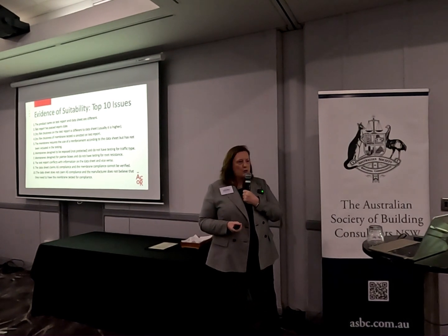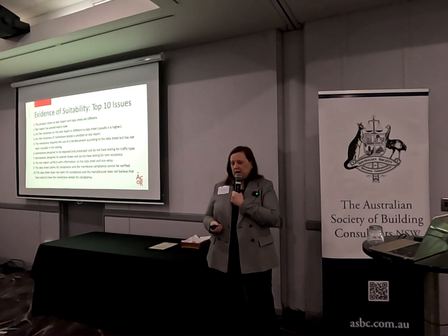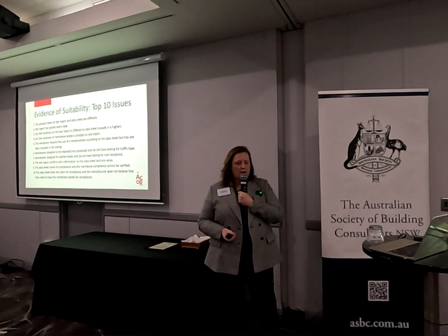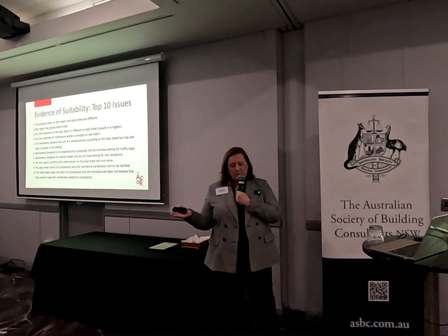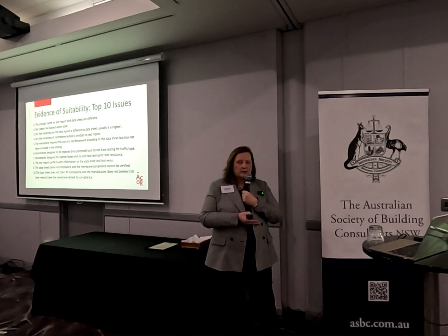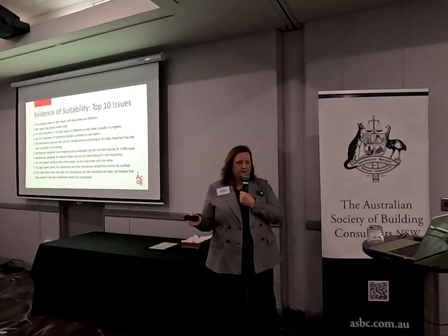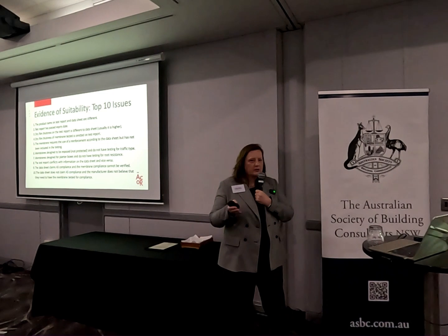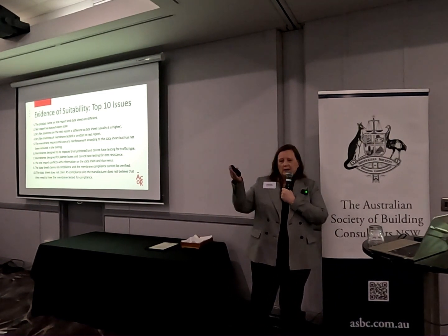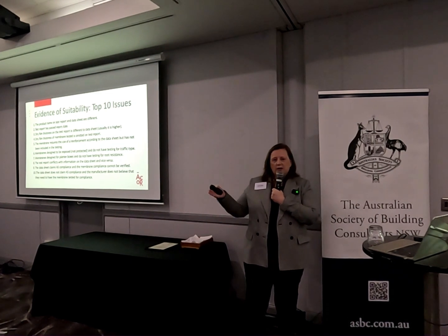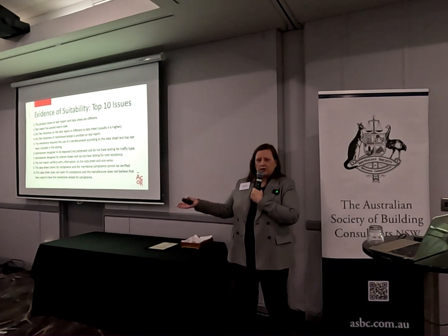Okay, the dry film thickness of the membrane tested is omitted on the test report. Now, this is a more recent thing. There are a couple of the ATLs who are not putting the thickness on the test report. And I've even seen a copy of an email from one of these labs back to a supplier which says, "we don't need to do that," which makes no sense at all, because what we're trying to do is verify that the product that is on the data sheet is the same as what's tested, and we can know what class it is and how to treat it.